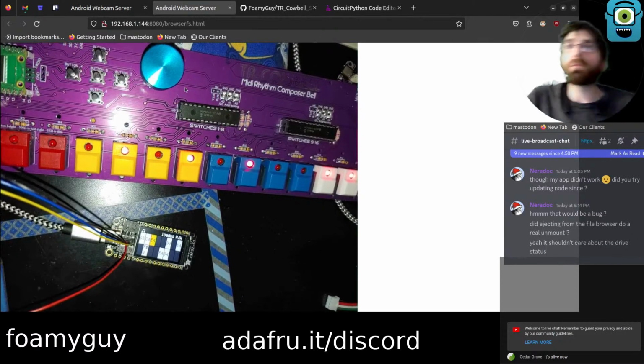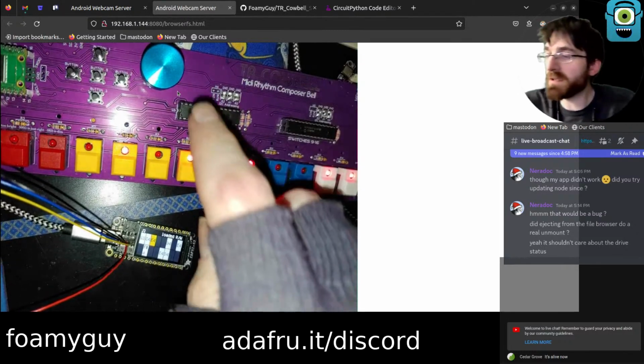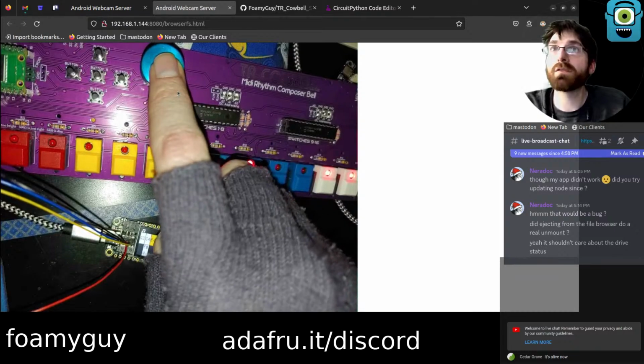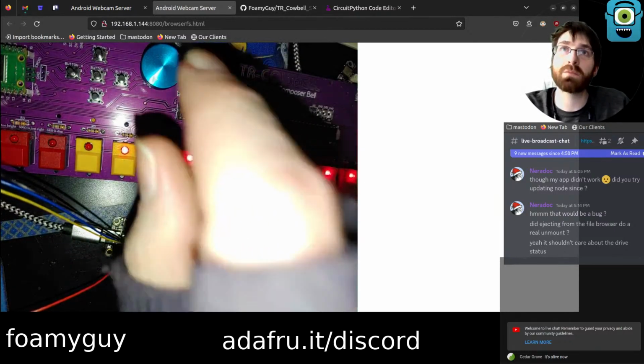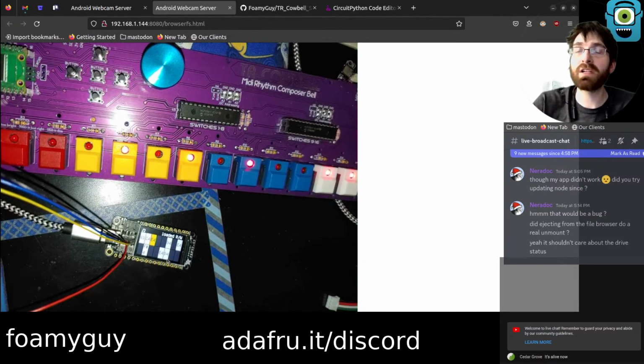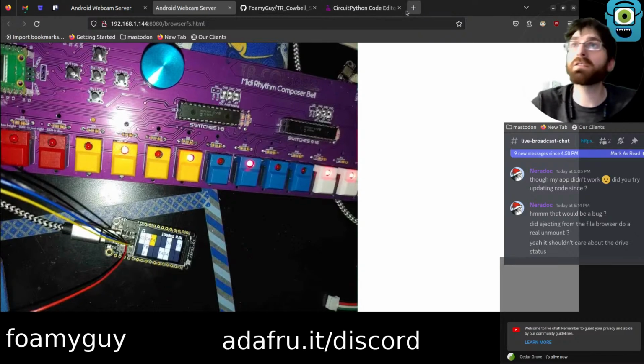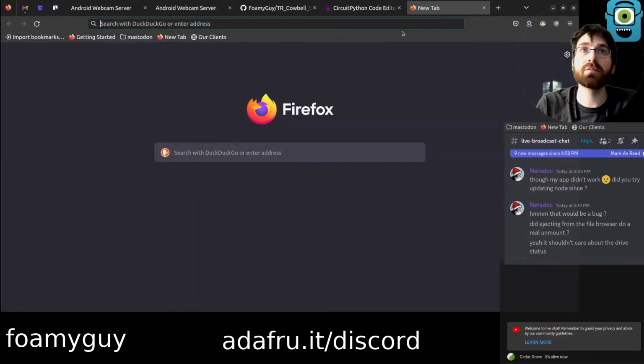Okay. What I would like to do now is on the rotary encoder, I want to play with the pitch bend a little bit. I want it to be if you press and hold the rotary encoder and turn it at the same time. So press it in and turn it. I want that to send a pitch bend. So it'll keep playing the sequence, but it will bend the pitch by some value related to how far you have turned it. I got this idea from another Midi project, which ran on a macro pad, which I should have kept a link around for so I could point folks towards it. But unfortunately, I don't know that I can find it very easily right now.